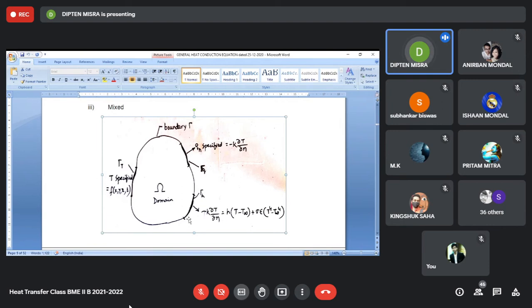But if there is a problem throughout for which we know only the heat flux or temperature gradient, that problem is ill-posed, and we cannot solve it. So for a problem to be solvable, we must know a Dirichlet type and/or mixed type boundary condition, because the mixed type boundary condition is also in a sense something where temperature is involved. So if this type or this type of boundary condition is specified, then we can solve the problem.